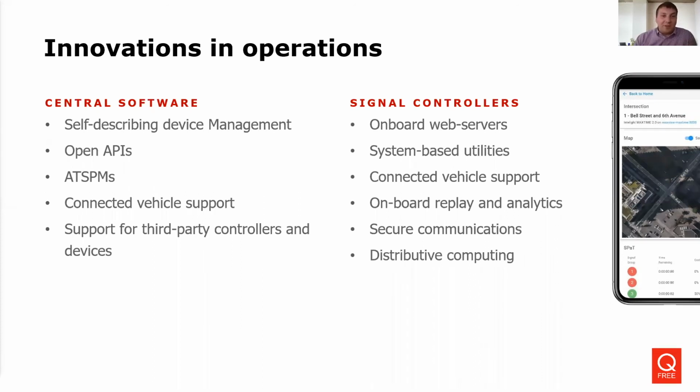Of course, connected vehicle support on the system side to push it up out into the cloud for anybody to subscribe to. And on the controller, again more technology, just bringing web servers to controllers. Instead of having special software on your laptop that you have to install and maintain separately, you can open a web browser, connect to the controller, and all of it's hosted there. This may not seem like some dynamite innovation to you guys outside the industry or that are starting into it, but I'm telling you, these are big things in the signal industry, and it's just speeding up. We need more innovation as time goes on. You can read some of these other ones if you have questions specifically.